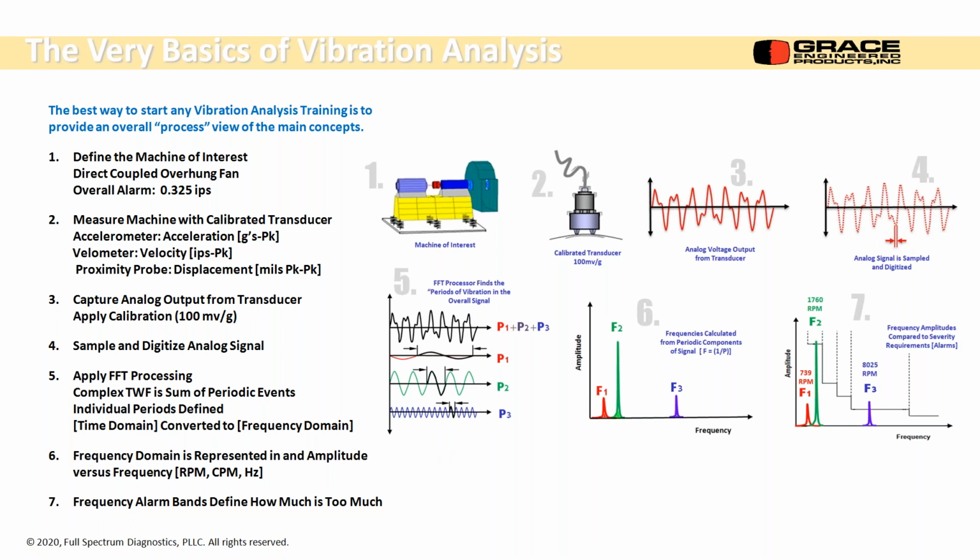A fast Fourier transform takes you from the time domain, which is here, into the frequency domain. Now we can see the amplitudes and the frequency content of that complicated signal, and 99% of vibration analysis is in the frequency spectrum. So this is how it's done. A simple equation: frequency is 1 over the period. We can go through it manually, but for complicated waveforms, it's much better to use the processor.